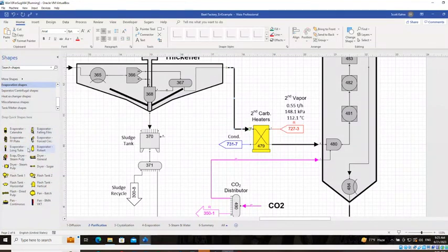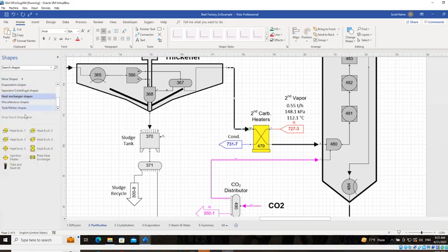All these utilize the same set of calculations, but they just have different pictures on the screen. And if you're talking about a booster heat exchanger, you can also set that up using a heat exchanger, essentially using a pump and a circulation flow through the heat exchanger just to recycle back to the evaporator.